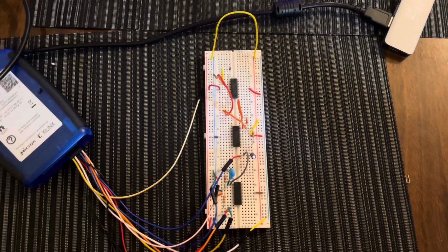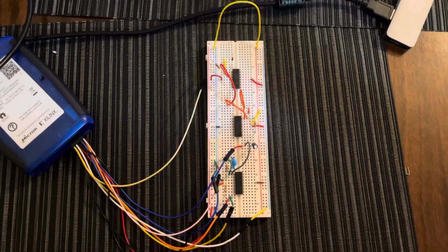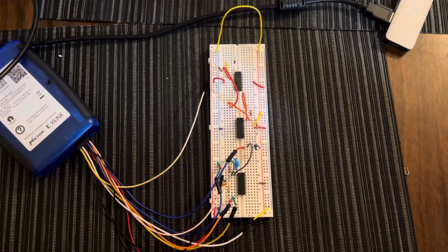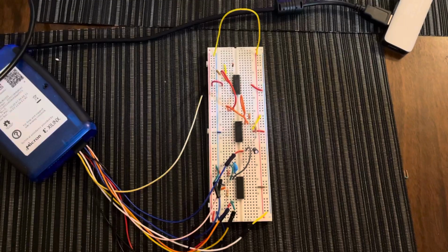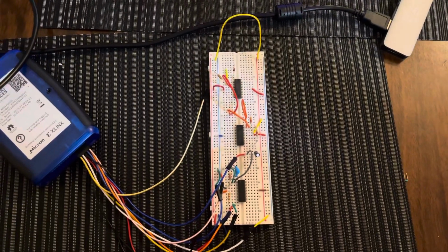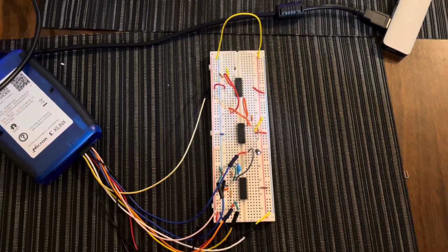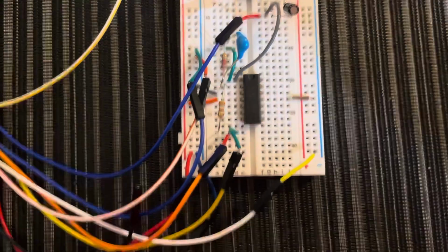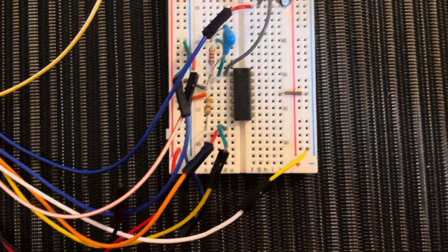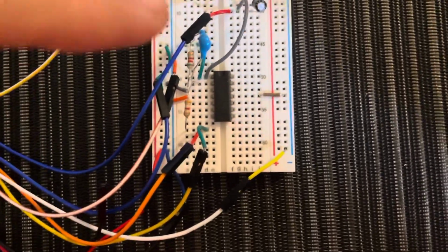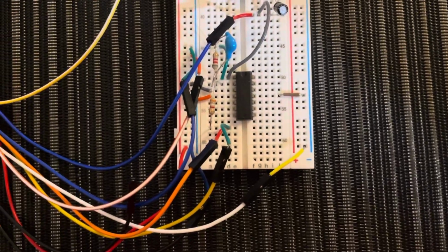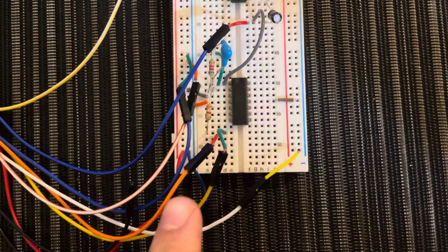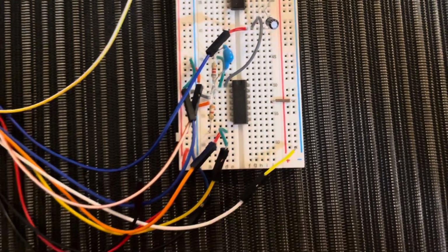In my lab, I decided to view what the effects of a low-pass filter, a high-pass filter, and an active half-wave rectifier would have on an input wave. So for the first subsection of my circuit, I have a low-pass filter, as shown by the op-amp, the resistor and the capacitor in parallel, and the input resistor that comes in with an input wave.